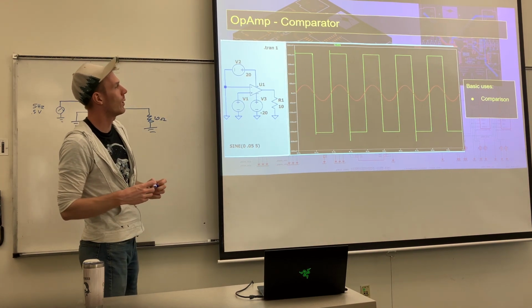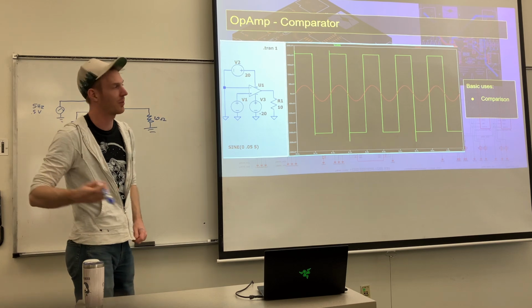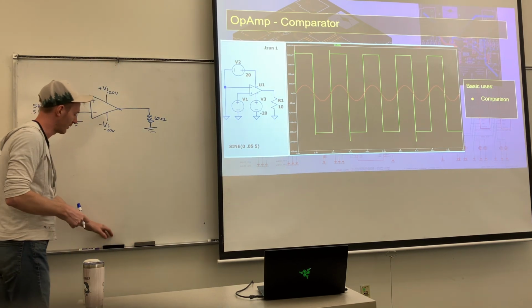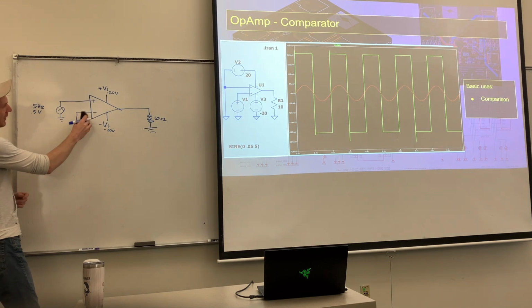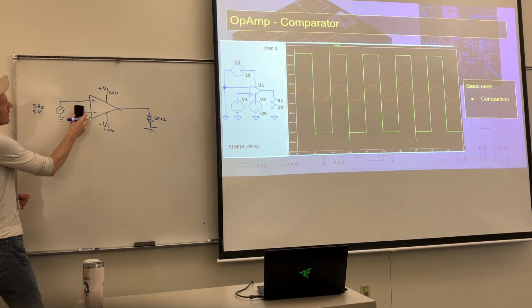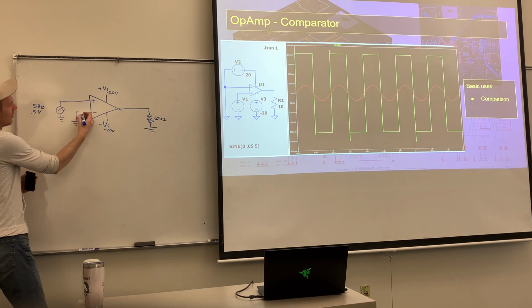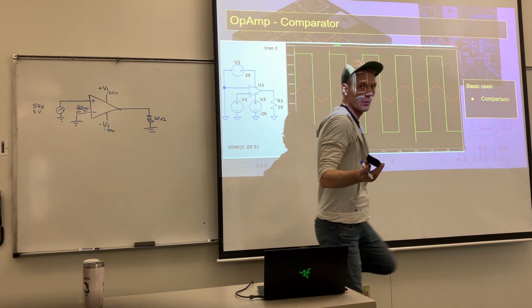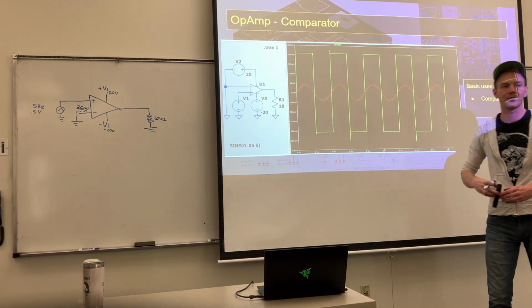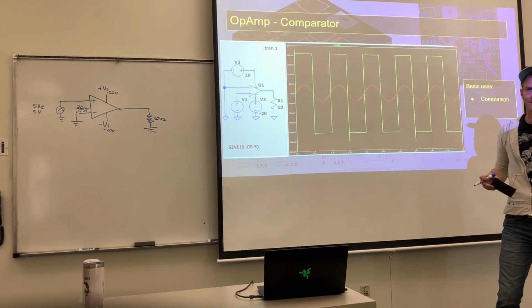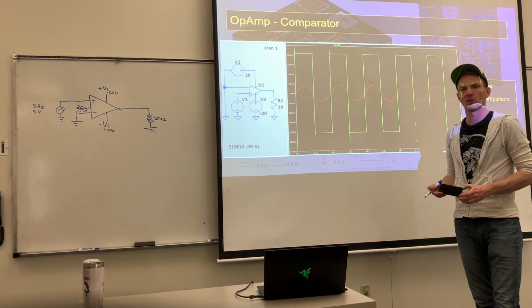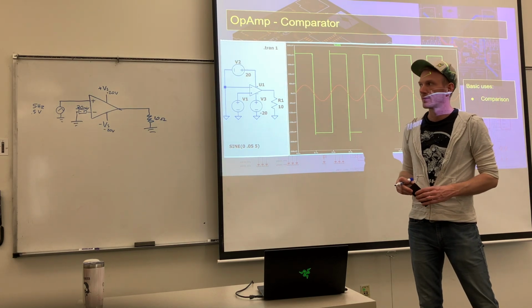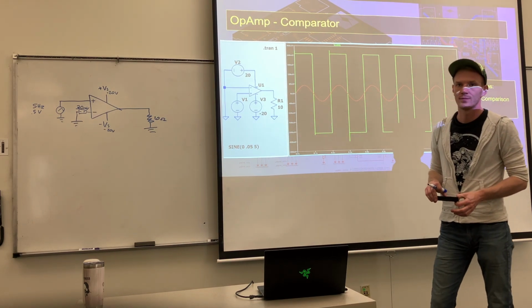If you want to actually compare it against something, instead of attaching this to ground, because basically we're comparing this against ground, you could put some other voltage in here. You could have a battery, right? Plus minus, and if this is at 30 millivolts, then, well, what do you guys think about it? If that's at 30 millivolts? Wait, how much is going into the plus end? 50 millivolts. Okay, so the gain would be like 20 times.